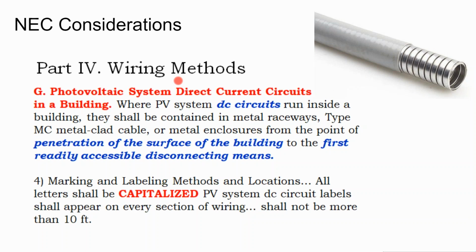And so often, like in multi-story apartment complexes in New York City, or conduit that goes alongside of a driveway, a local jurisdiction will step in and say you've got to use rigid conduit or intermediate conduit, which is a little bit thicker than standard conduit, to give it additional physical protection. But it's not something that has to do with DC specifically.